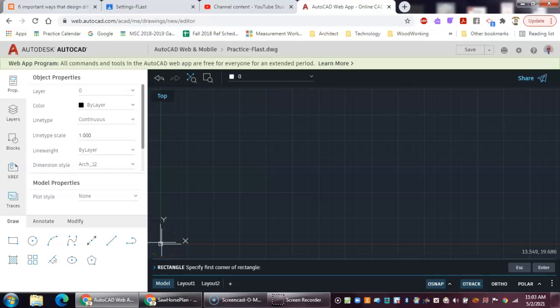You can see from the way our perspective is right now, just by looking at those coordinates on the screen, we are zoomed way out on our drawing area. So I'm going to go ahead and enter this, and then we'll talk about the sizes, because I want you to remember when you open this up, it's kind of a wide screen here. So I'm going to type 3, 2 and hit the enter key. So that basically puts that corner on my part.